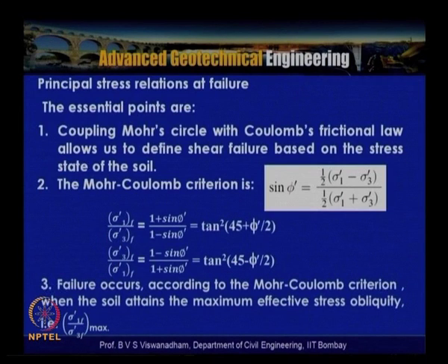So the important points which have cropped up from the discussion are that coupling Mohr's circle with Coulomb's frictional law allows us to define the shear failure based on the stress state of the soil. So that is what we call the Mohr-Coulomb failure criterion. The stress state of the soil at a given level can arise due to how we apply the loading. So the Mohr-Coulomb criterion, for granular soils, when it comes